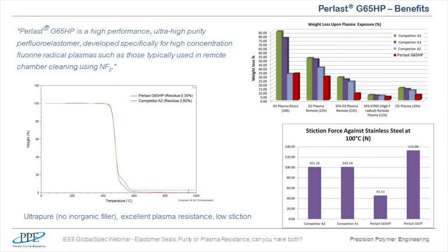Another important property of elastomer seals is the stickiness. Fully organic materials usually become very sticky when they are exposed to heat. I've been hearing engineers always complaining about the O-rings sticking in a groove when they want to replace them. Some of them need to use tools to remove the tacky O-rings from the groove, and they spend quite a lot of time. In some cases, they even damage the groove.